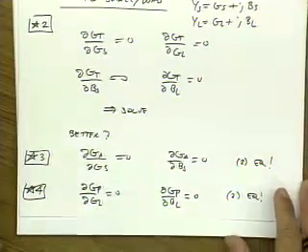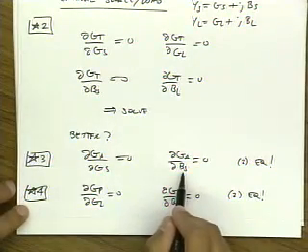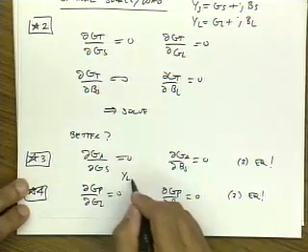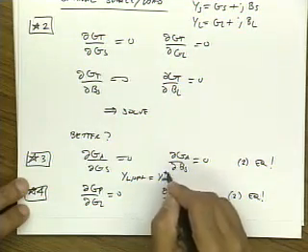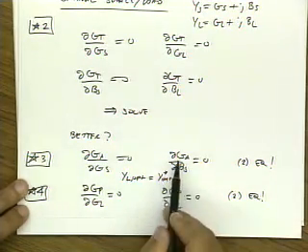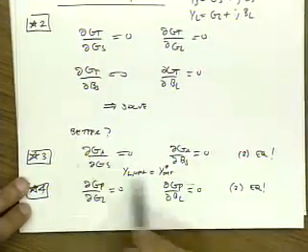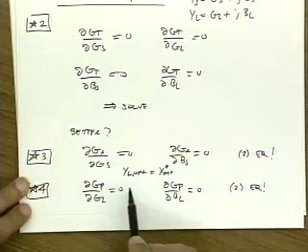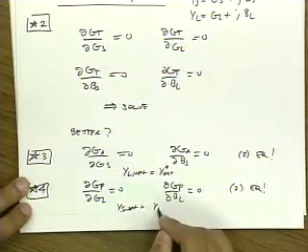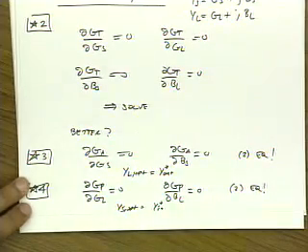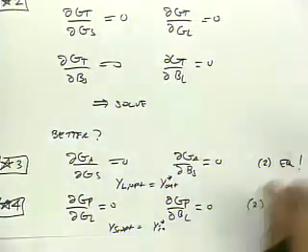And when you're done, so for instance, if I solve for GS opt and BS opt from these two equations, I can find YL opt by simply making YL equal to Y out star. And Y out, remember, is a function of YS. So this is a recipe for finding the optimal load. So even though this only gives us the optimum source, with one line of algebra we can find the optimum load as well. And here, YS opt we can find by doing the same thing. Okay? Any questions about that? Does that make sense? Good.